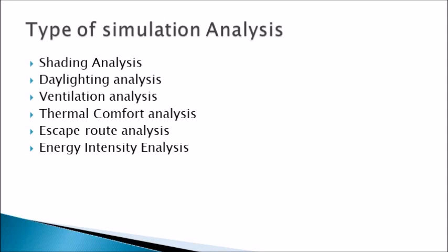Similarly, in daylighting, if you provide enough good daylight harvesting in your building, then the simulation software will take the daylight harvesting as a discount against the actual energy needed for providing lighting in your building. Okay, so the resulting energy intensity is the value or the quantity that you would use to report the performance of your building in GBI and MS 525. So you can see how important it is for you to understand or to be able to use building energy simulation.